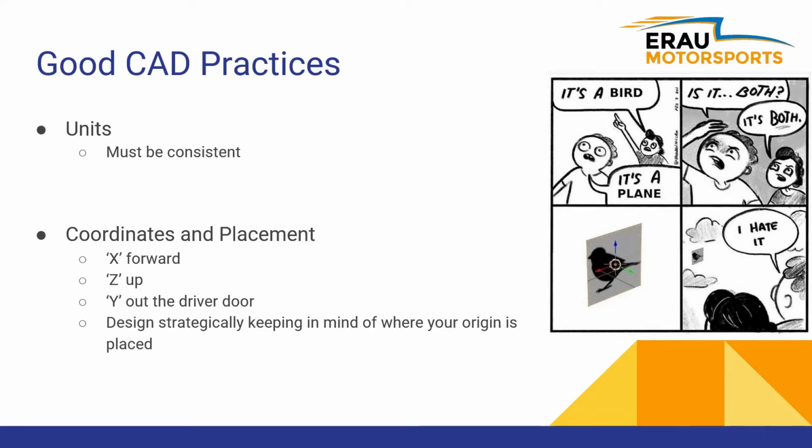Usually you want to design your model with the origin being right below the center of your front wheels, touching the ground, accounting for the squish of the contact patch. Or if you're modeling airfoils or bare wings or just models without wheels, then design a model with the origin at the very front of the model.